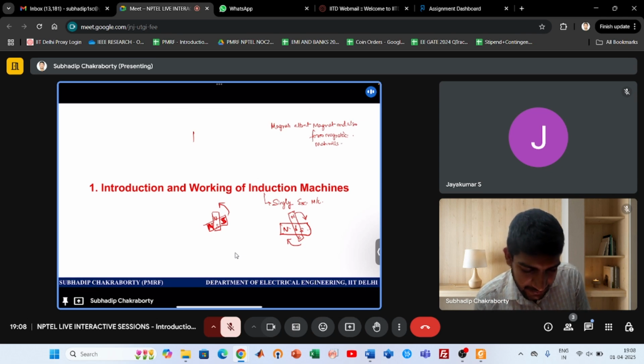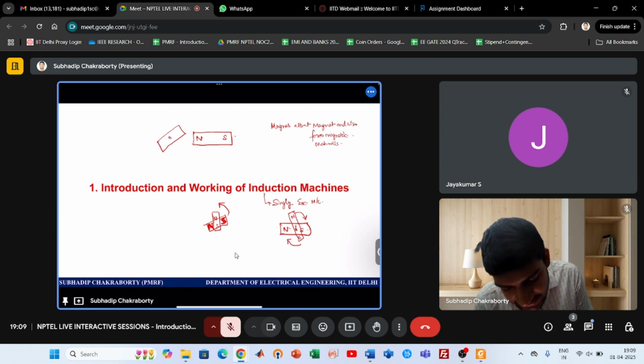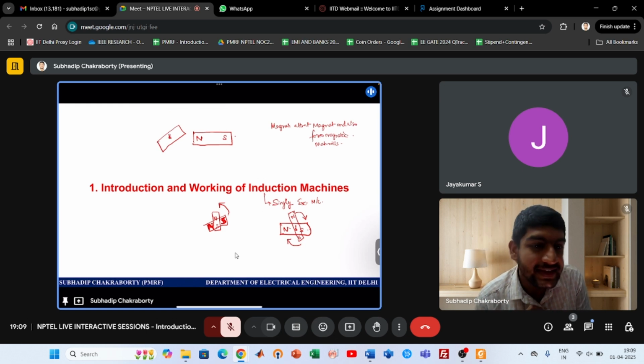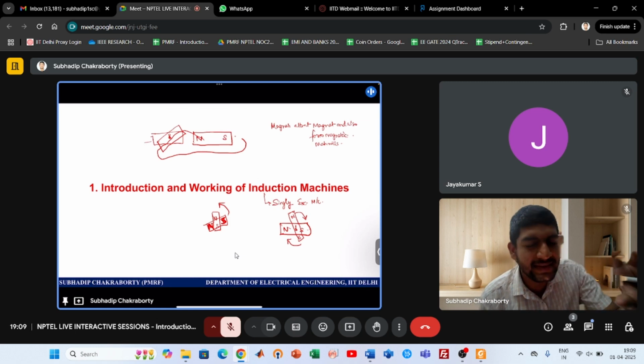Like for example, you have a magnet like this, and you have a piece of iron like this, and you force it along a path, a hinge. What will the iron do? It will try to align with the magnet like this, because magnetic flux lines find it easier to pass through an aligned path rather than an unaligned path, which they would have to traverse more.